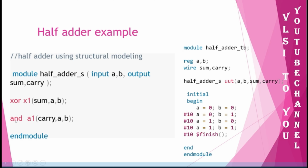Since it is gate level modeling, you just need to give what type of gate it is, because these gates are already built into Verilog HDL. That means they are gate primitives, already designed within it. So you just need to mention the gate type, like this is XOR and this is AND. For the XOR gate, you name it X1; any name is fine.